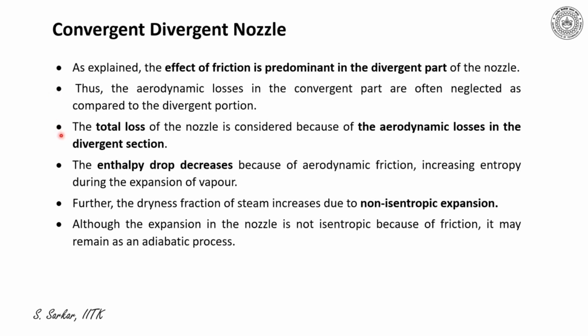Hence, the total loss of the nozzle is considered because of aerodynamic loss in the divergent section. Now, the enthalpy drop decreases because of aerodynamic friction, increasing entropy during the expansion of vapor inside the nozzle. Further, the dryness fraction of steam increases due to non-isentropic expansion.